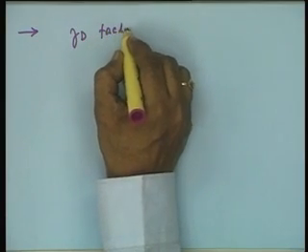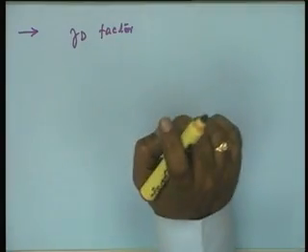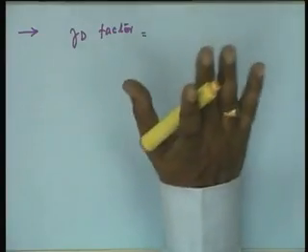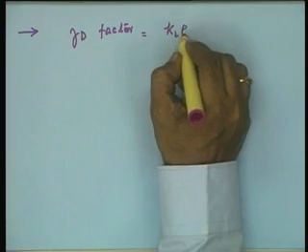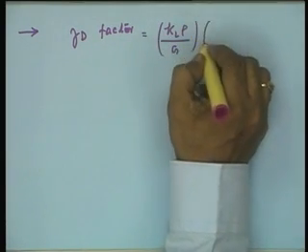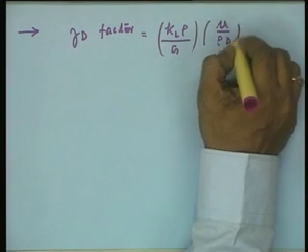And so, another alternative route to estimation of mass transfer coefficient has been on the basis of some empirical relationship, what we call as JD factor. Now, a JD factor has been defined in the case of heterogeneous catalysis in chemical engineering in general, and of course, which applies very well to even enzyme catalyzed reactions, and JD factor is defined as a lumped parameter which takes into account the mass transfer coefficient, particularly film diffusion coefficient, as well as the reactor operational parameters. The JD factor is your KL rho upon G into mu upon rho D to the power 2 by 3.